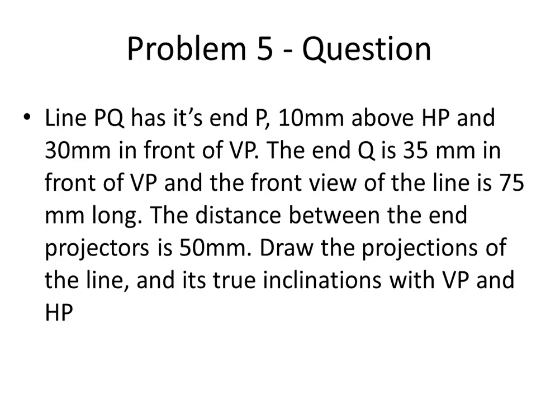So this is a typical problem where you would be using the plane rotation method, because the hint for this is the distance between the end projectors, and you are not given the true length here. So let's start by looking at the technique, how this could be done.